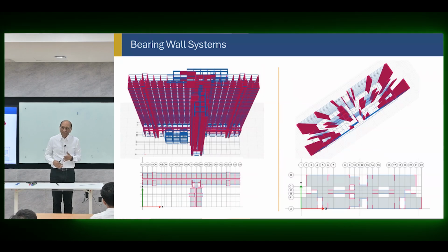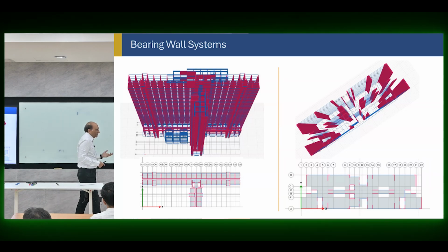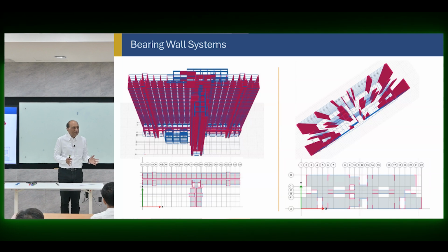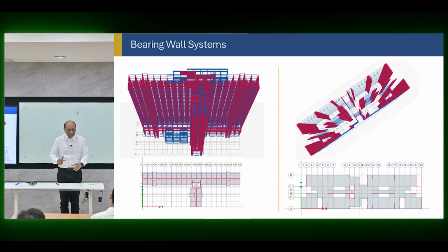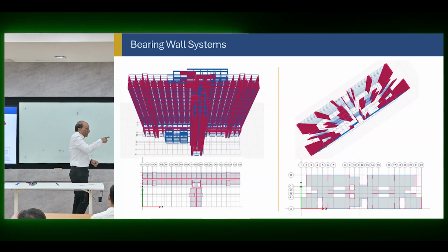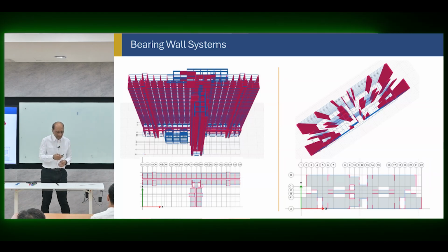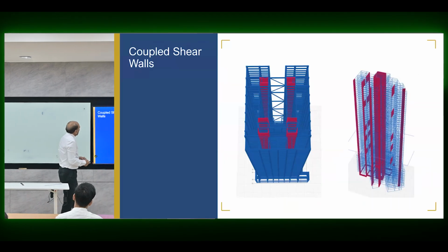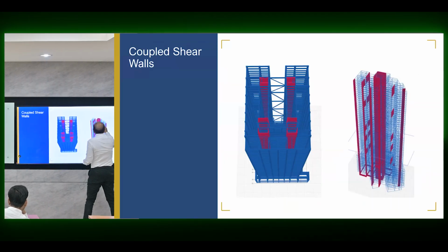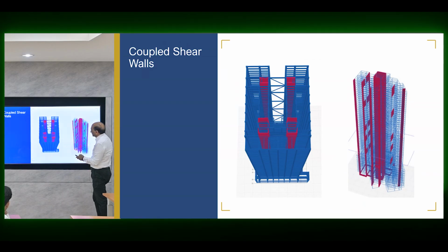Construction-wise, cost-wise, speed-wise, fantastic. And in Bangkok, the Bruksa company has built a precast system. All the wall elements are precast, all the slabs are precast, so it is very easy to make. And they just have a single core which is holding everything together. And these precast walls are post-tensioned, so they are acting very nicely together. AIT helped to design that system. Coupled shear walls here, as you can see, so we have the coupling between them.